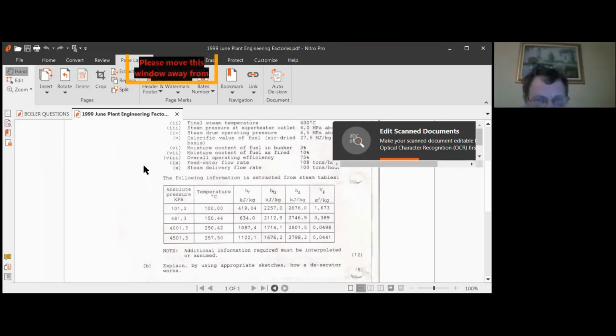Look, I think that's probably more correct, but between the feed water flow rate and the steam, there's 8 tons per hour that got missing. I'm not sure if that's leaks or stuff like that. But at the end, I only used the 100 because it's the difference in enthalpy, and the amount of steam that I'm actually going to send to the turbine is the one that matters. But I think you're 100% correct, and it's more correct to do it like that.